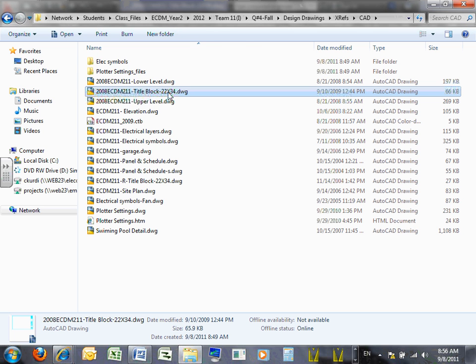That's why we do the XREF. So when the architects update their background, and if you're XREFing to them, every time they work on their background and update it, you will see the most updated version of this background. Does that make sense? That's what XREFing really is. You're looking at a picture right underneath it, and every time the architects move the picture and you are looking at the top, you can see what they have done when you upload. Okay, that's why if you work on the file itself without XREFing, you can't see what the architects are doing.